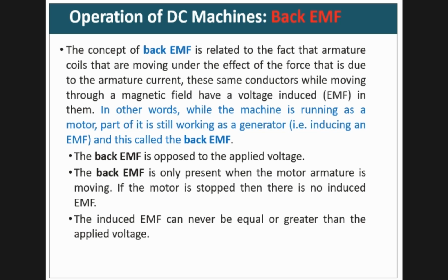In other words, while the machine is running as a motor, part of it is still working as a generator, because the coil is moving in a magnetic field, so it is going to act as a generator as well.